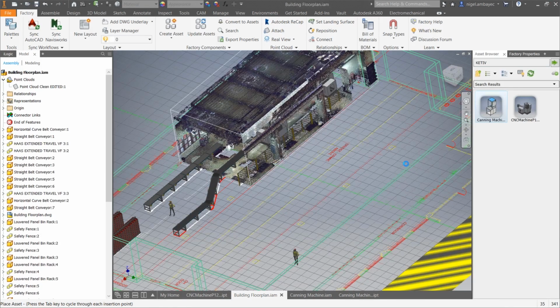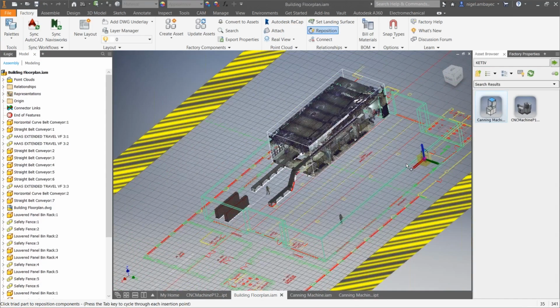All right. Is there a good way to prepare an Inventor assembly to become an asset? If you've automated features, will the constraints be stripped? So yeah, like I said, best way to do it is to shrink wrap those assemblies, make them a lot easier to consume. In doing so, you get rid of a lot of those assembly features. And if you don't make it associative, then you're good. And then you just create that asset like I did earlier with this particular canning machine, and you're off to the races.